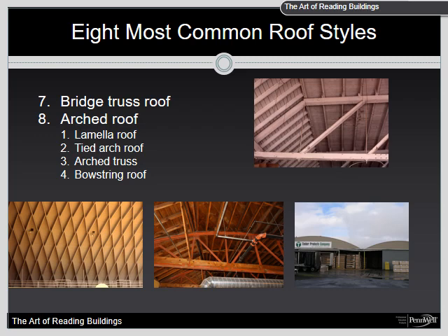Lastly, remember that the ends of the building with this roof can present a primary collapse hazard. If jack rafters have been used to slope the roof downward from the last truss to an exterior end wall, the end of the jack rafter will forcibly push the corresponding end of the wall outward if the end truss fails.